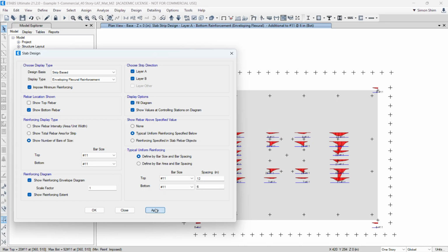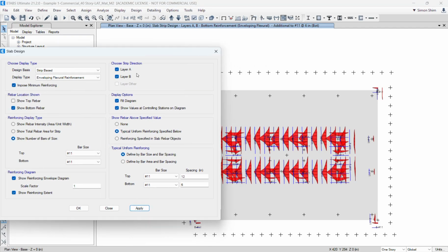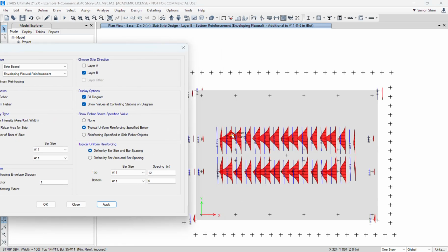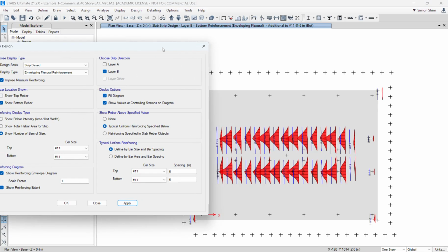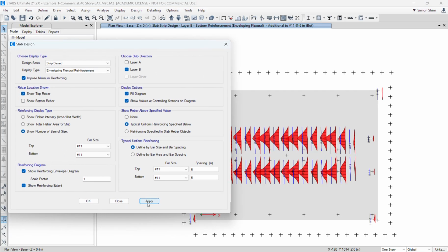All right, let's take a look at it in the Y direction. It's pretty much the same. I turn up the A direction. It's pretty much the same, right? Under the wall, you see more reinforcement is needed, so that I can add it here. Top bar, bottom bar. Okay. Bottom bar, and I'll change to top bar.